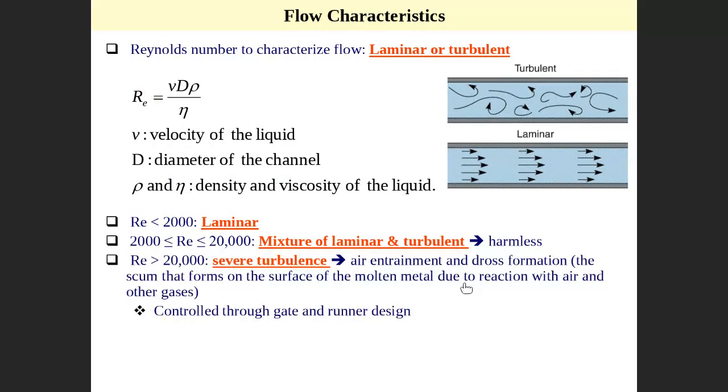Next, we always need to be sure that the flow is laminar, with no turbulent flow in the mold. I mean the liquid metal is in a laminar flow, not turbulent. We are always concerned about that. Even though we avoided aspiration previously, and designed to avoid it by maintaining velocity at a certain level to avoid trapping gas inside and porosity in the material, there is another way to check.